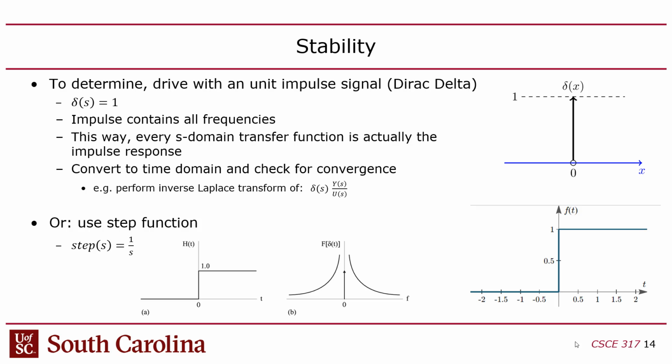let's see. So there's this thing called an impulse response. This is the part that always confused me. I understand the transfer function, right? The transfer function is telling you how an ODE changes a signal, right? And how does it change it? Well, it can change the phase, and it can change the amplitude. And it can change the amplitude differently at different frequencies when you send a sinusoid in it, right? So that's what a filter does, right? It attenuates certain frequency bands, and it puts gain on other frequency bands. You can do low-pass filters and high-pass filters and band-pass filters, right? So that's what a transfer function does.